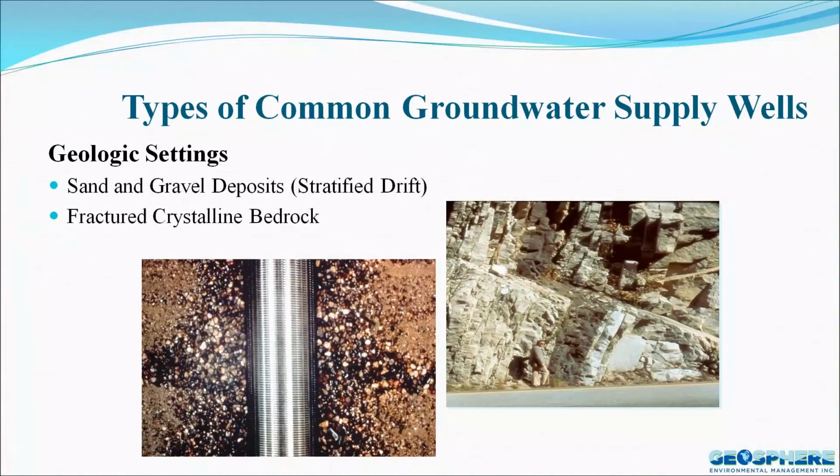These little cartoon diagrams, the first on sand and gravel deposits and sort of stratified drift, which Ted was talking about, which is the material we want to look into because that will give us our best aquifer transmissivity, will give us the higher volumes of water. And the little diagram on the left is kind of interesting because we have our well screen inside, and then on either side of it we have our gravel pack or a natural one.